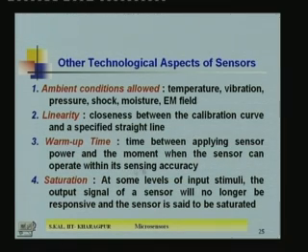So, sensing accuracy is important. As soon as you switch on, you may get some output, but the output is fluctuating and not stable, which we cannot consider. It has to be stable and within the accuracy limit specified by the manufacturer. When it comes to that level, then we call it okay, and that time we count as the warm up time. And another one is saturation.